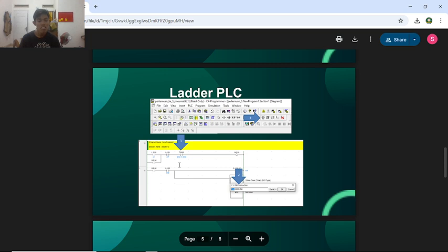And insert a timer in the ladder diagram. After the cylinder extends fully and activates limit switch 1, the PLC starts the timer. The timer waits for a preset duration, for example 5 seconds. After the timer expires, the cylinder retracts, so it will go back to its original form.